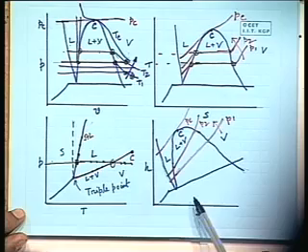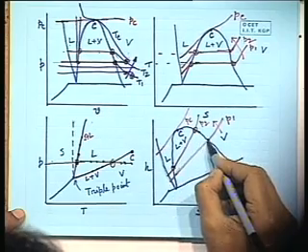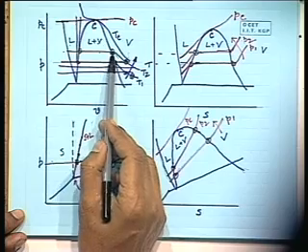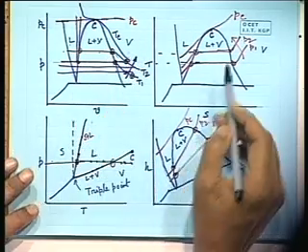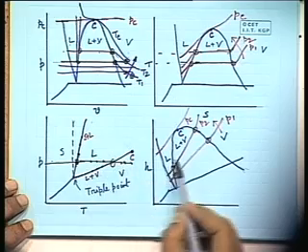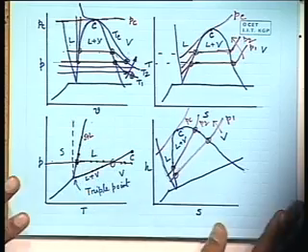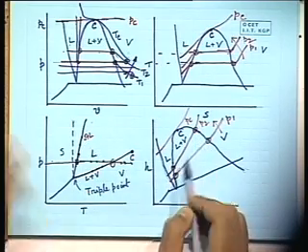This is the TS, this is the HS. So these points are the saturated states. And here you see there is a change in the specific volume during this change of phase. There is a change in the entropy. There is a change in the enthalpy. That's why these points are spaced apart. But in PT diagram they are the points. So these points are known as saturated states.